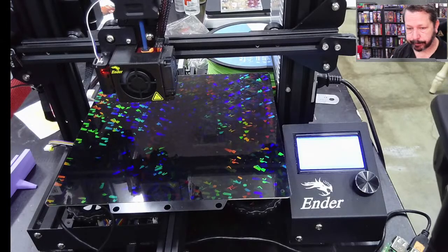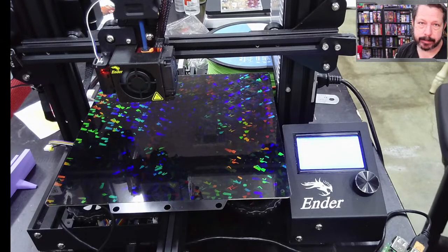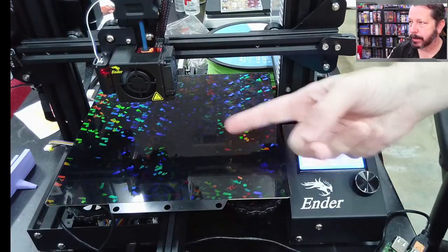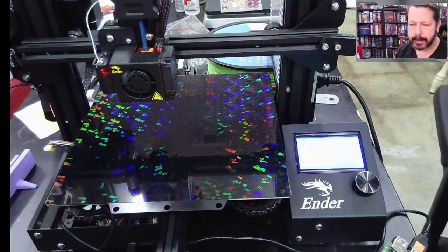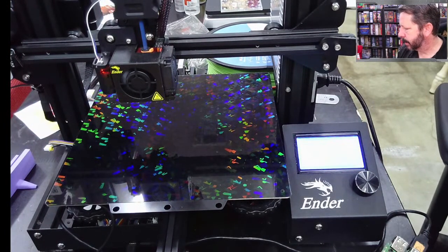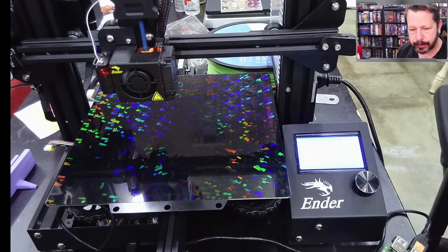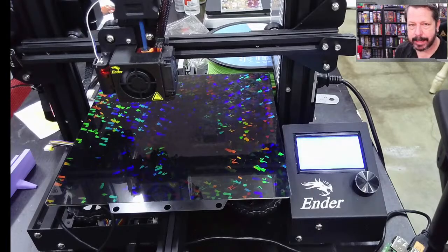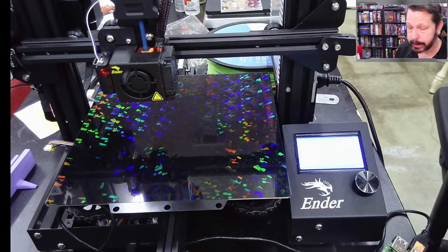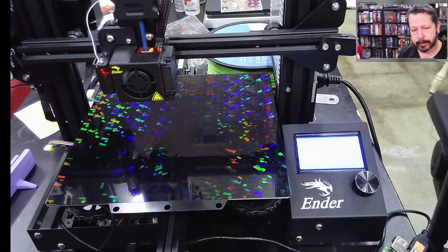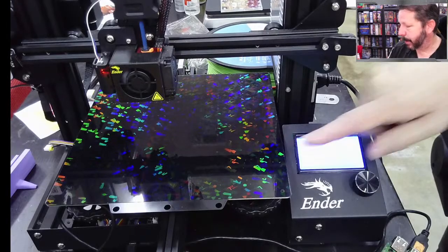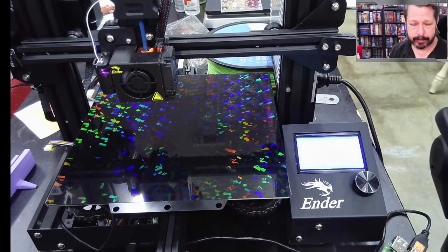Cura's loading. We'll just try to print some kind of flat sheet. Basically all we're interested in is how well this transfers. Now I do know that this printer doesn't like printing too close to the bed, so that might be an issue, because it does need to squish down into the bed pretty well. I've got it set to where this one does not squish too much, so we can adjust that a little bit, hopefully. I don't want it scraping into the surface though. That's not what we want.